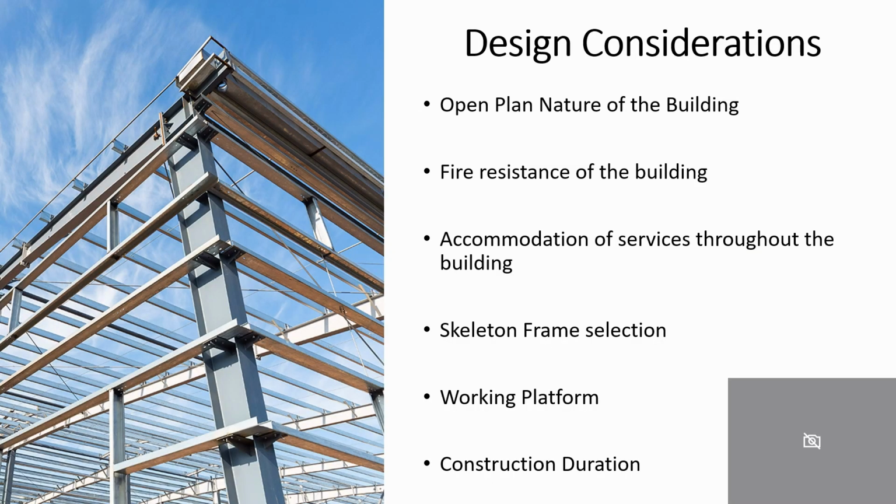So some of the design considerations I've made. Due to the uses of the quayside tower and the open plan nature of the building, concrete hollow core allows for large spans across the building with an integrating heavy load bearing capacity. As well as that, the concrete flooring gives the appropriate fire resistance in accordance with Part B of the fire safety due to the tenanted upper floors. Given that the slabs incorporate a durable soffit ready to accommodate surfaces, this means a much faster construction period when it comes to the installation of the surfaces.